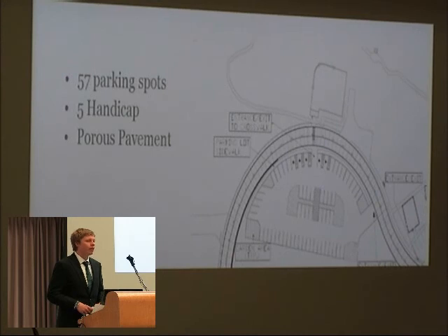Our restaurant parking lot has 57 regular parking spots with 5 handicap spots. The handicap spots are ADA compliant, and we have one van accessible spot. We also have a sidewalk that runs around our parking lot to keep people from walking through the parking lot. And from each access aisle in the handicap spots, there will be ADA compliant ramps to reach the sidewalk.